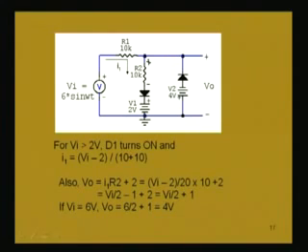So, let us consider the limiting points, the peak voltage. Starting from 0, the sinusoidal waveform has 6 volt as the peak, Vi is 6 sin omega t. What will be this voltage at 6 volt? You put this value in 6 by 2 plus 1, that is 4 volt. That means, when the input voltage is 6 volt, your output voltage will have a value of 4 volt. So, it will be like this. Now we get the output voltage waveform for the positive half cycle.